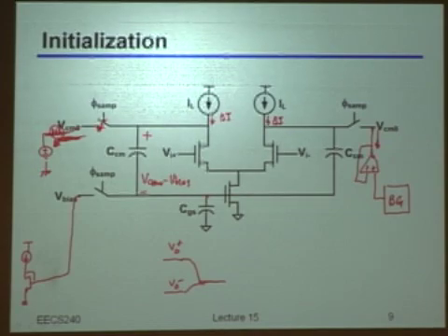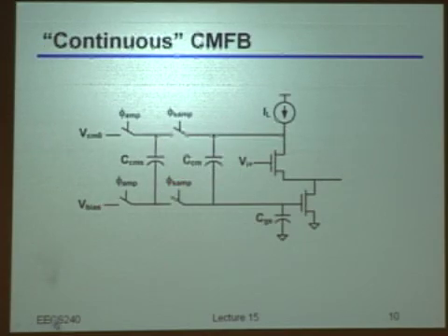So is there any, let's say, more delicate way of performing this, right? And actually, there is one. I mean, there are plenty, actually, many variations. We will go for the typical one, which also has the advantage of providing you possibilities of using the amplifier every time. So most of the time, in switched capacitor circuits, it can also happen, especially when you implement a filter, that you are going to use the amplifier for all the phases, actually. It's doing something good and something useful, both in phi 1 and phi 2, right? But in both phases. So in these cases, actually, this is a little bit different.